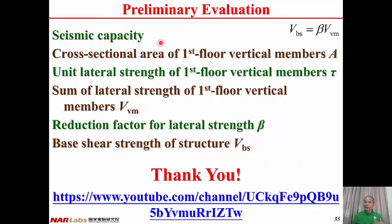And in this lecture, we focus on the seismic capacity of a building by preliminary evaluation. In order to calculate the seismic capacity, we have to know the cross-sectional area of the first floor vertical members. That means a professional engineer has to arrive at the school building and measure the cross-sectional area of first floor vertical members, including reinforced concrete columns, reinforced concrete walls, 4-side bounded brick walls, and 3-side bounded brick walls.